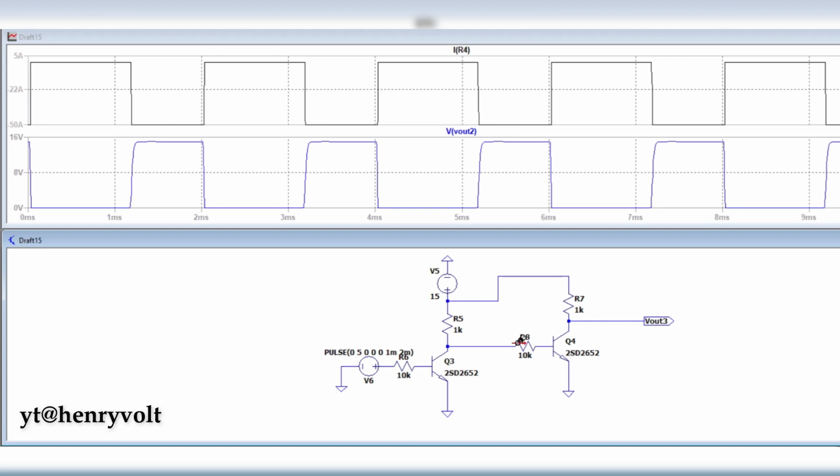Since the input and output of an NPN are complementary in nature, Vout3 will be similar to the input side microcontroller output voltage. We get one complementary, these two are opposite, then we make it complementary again, then we get similar. So basically it's two inverters in series.